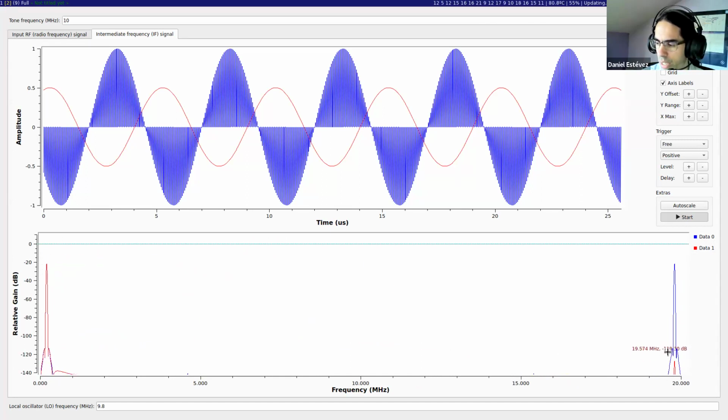But if we look at the high frequency signal, we can see that in the output of the filter, so in the red curve, is still present, but it has been attenuated by a lot. So this is minus 20 dBs, more or less, and this is minus 130 dBs or minus 120 dBs. It is minus 100 dBs of attenuation, which is a very large attenuation.